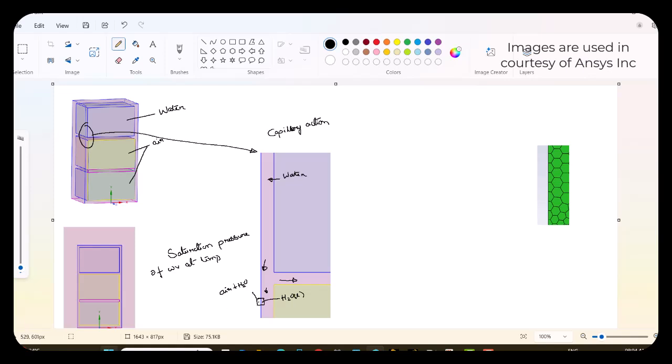Now the water vapor fraction with 50% RH, for example, means the mass fraction would be around 0.028 for a temperature of 300 Kelvin. So there is a chance of an extra 50% RH that can be accommodated into the cell which is adjacent to this wall.